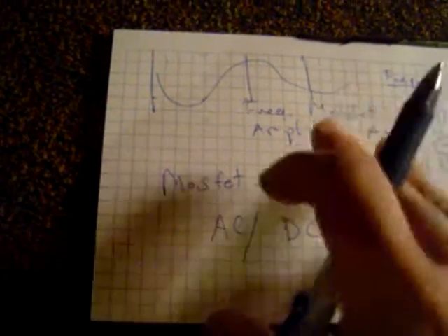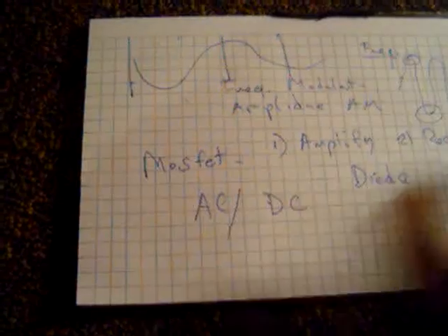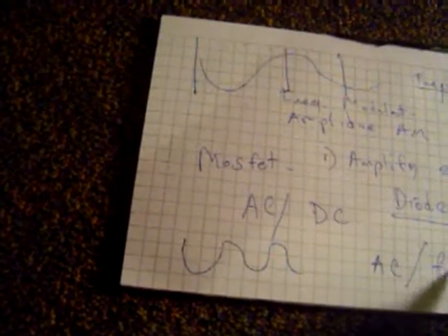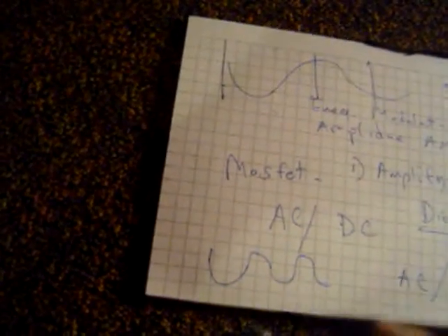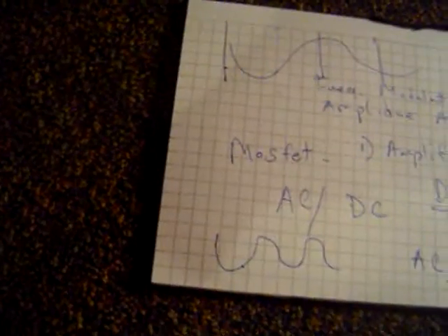So the original OEM has what they call a diode rectification process, where it only allows current to go in one direction. Now, what do I mean by a diode in one direction? A sine wave, or AC, depending on the frequency, will change directions according to the frequency.